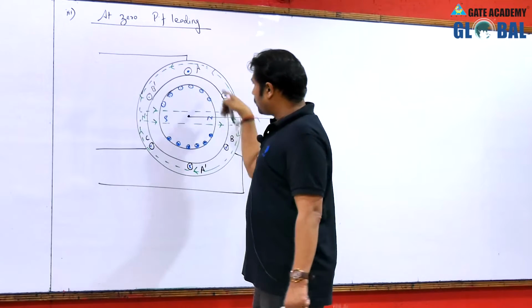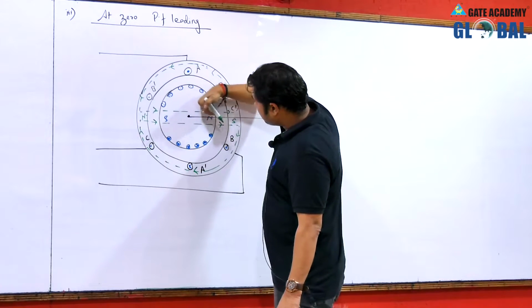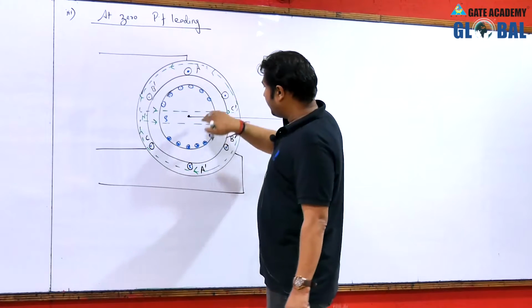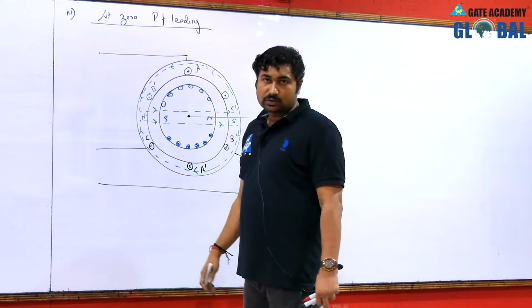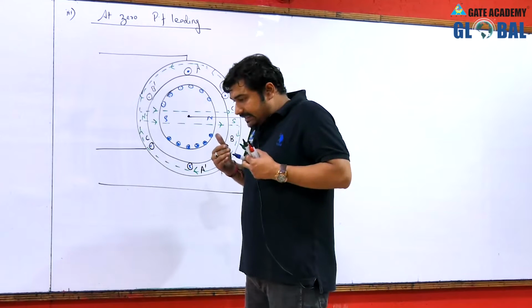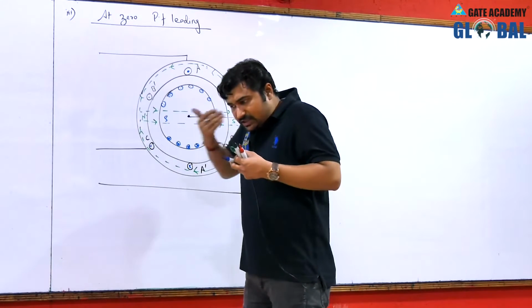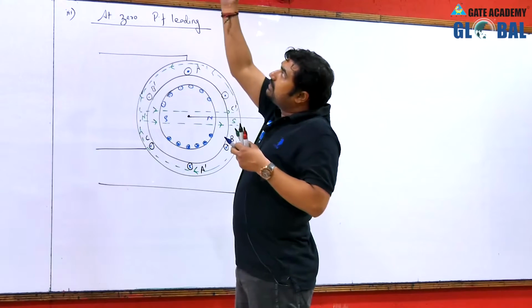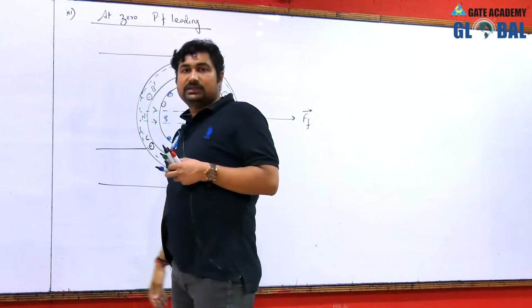However, in case of the rotor, if you observe the rotor as an iron part, in this iron part flux lines are coming out from this portion and going into this portion. That is why I have marked this as a north and this as a south. Always remember that the stator is observing the rotor. So, the stator field is coming out in this fashion, while the rotor is observing the stator. So, rotor north is supplying the magnetic lines of force towards the stator side.